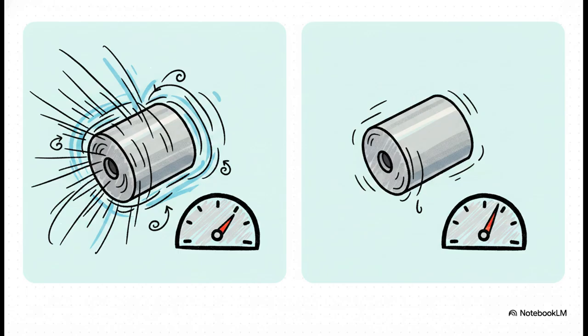Soft aluminum, you can turn that screaming fast. We're talking over 1,000 SFM. But hard titanium, you are severely restricted to around 150 SFM. If you choose the wrong speed for your material, for sure you are going to cause premature tool cratering or thermal cracking of your insert.